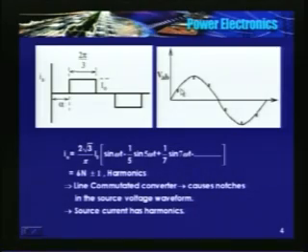The last one is electronic equipment. We found that the source voltage itself has notches. Now your control circuit may sense that this is a zero crossing. Actually, there is one zero crossing here, and if the system impedance is high, the notch may become zero here.